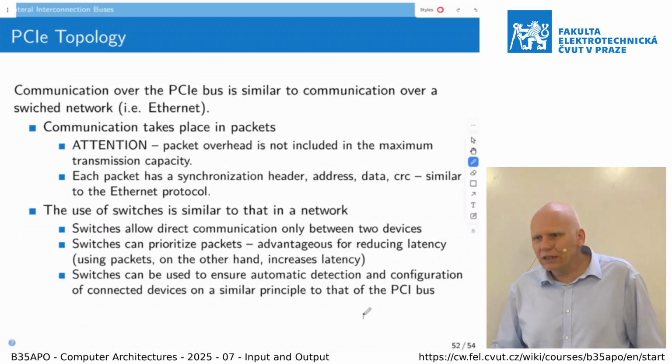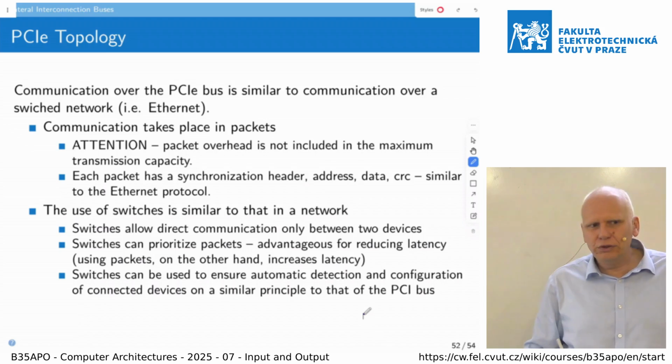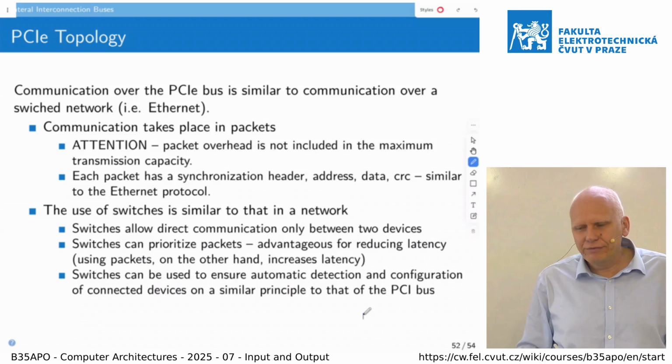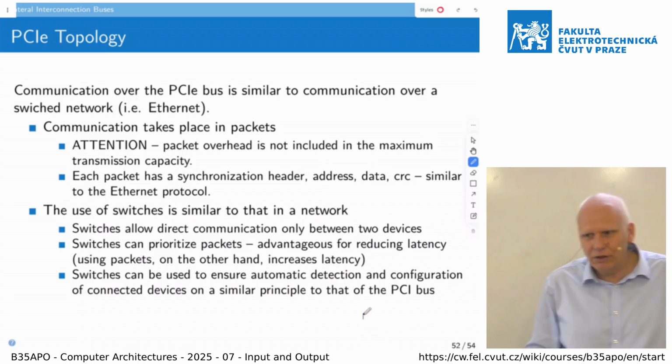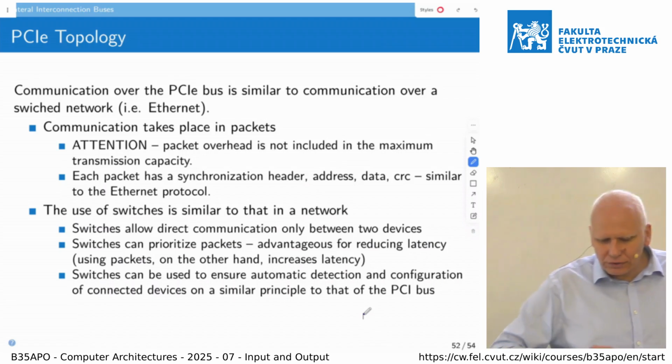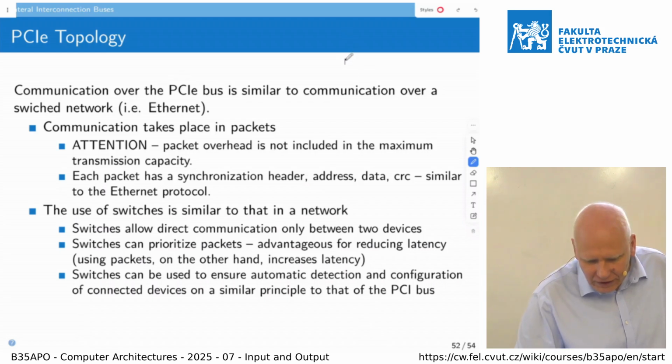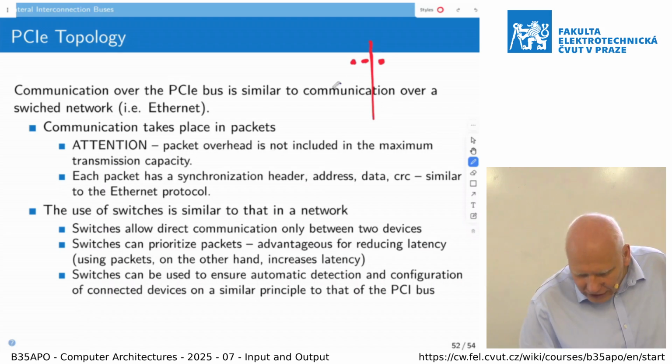If you know quadrature amplitude modulation, which is used for video broadcast, if you have digital video broadcasting, DVB, terrestrial or cable or satellite, then it works in such a way that you send the data at some frequency and you modulate by amplitude and by phase shift.